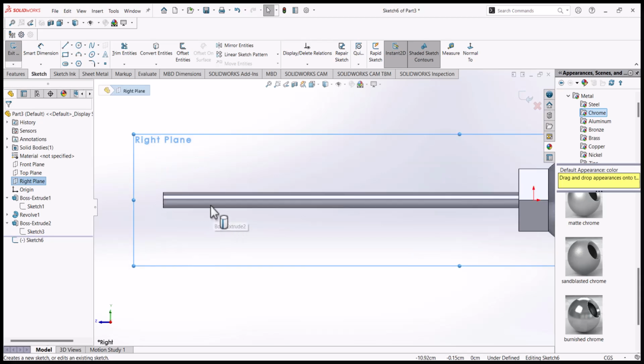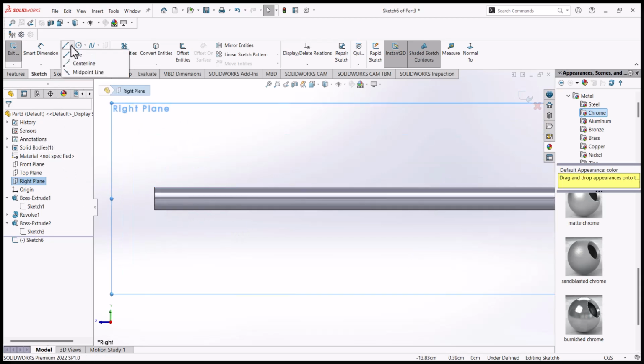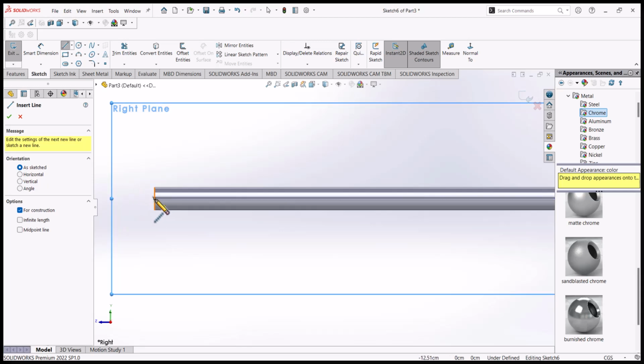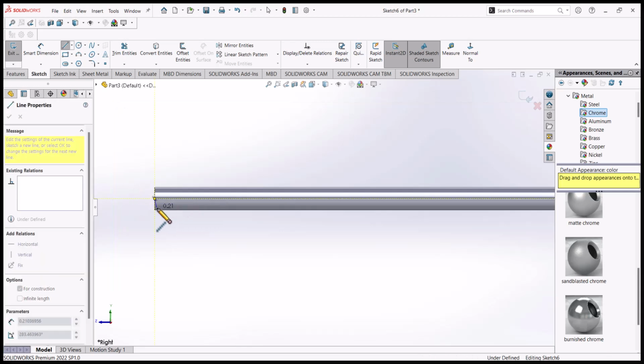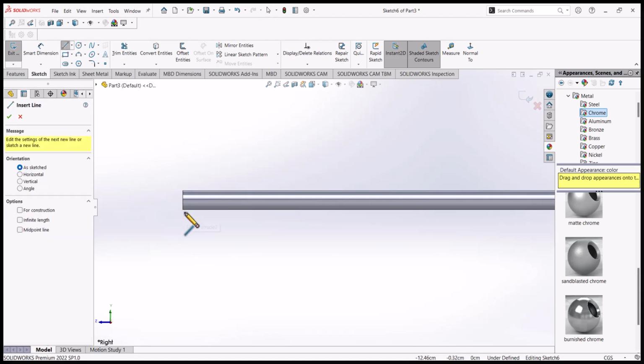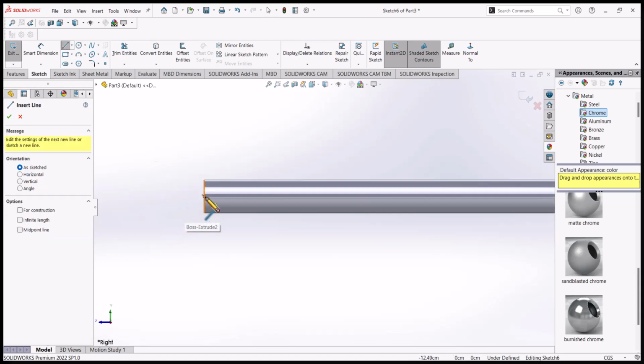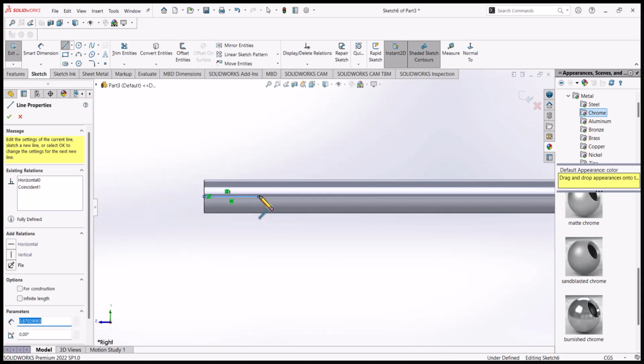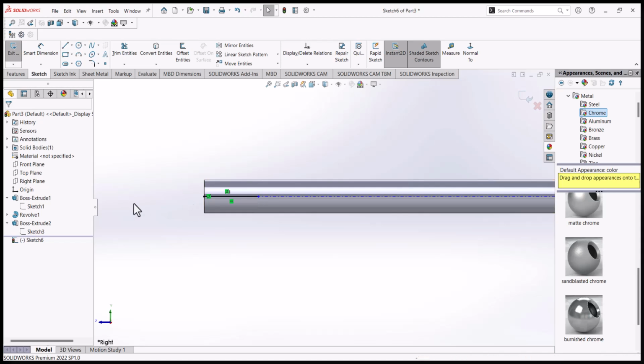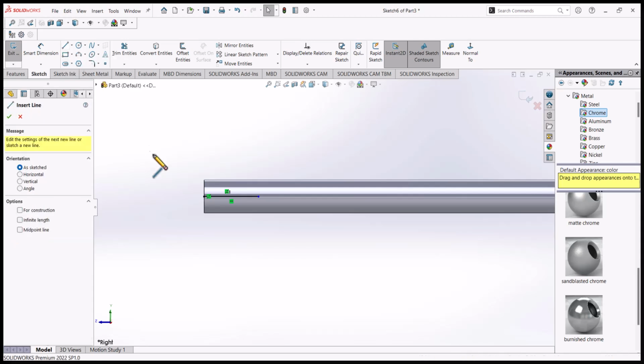So this, I want to make a flat screwdriver. Center line. You see, for example, when I go here, when I select line, immediately I bring it to this edge. I get this yellow line. You see that yellow thing? That yellow thing signifies that this is the midpoint. Okay, you get it? That yellow thing signifies that this is the midpoint. So I draw to this point here. Good. So now I want to select line.